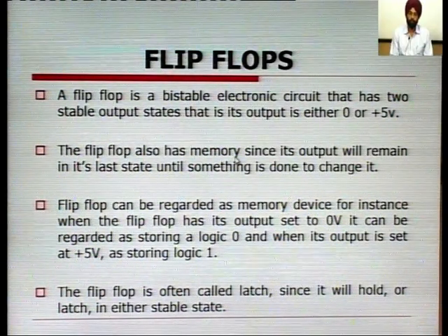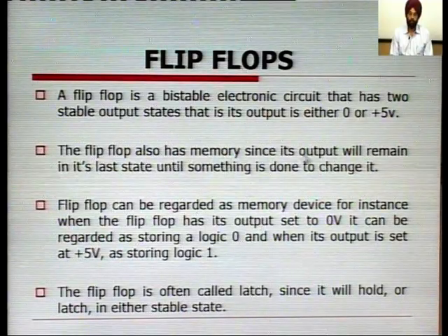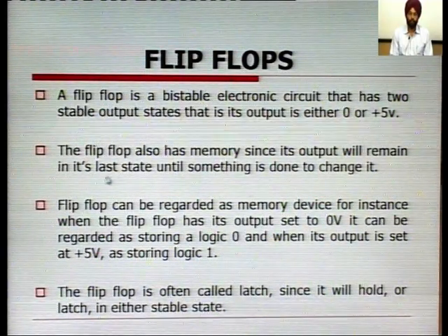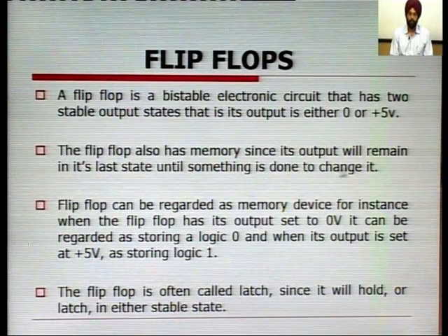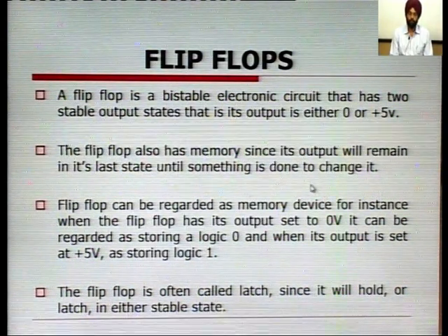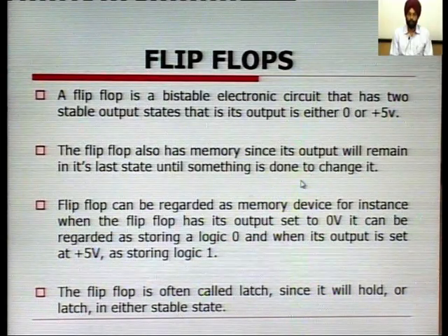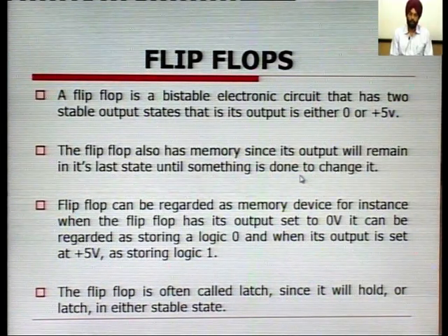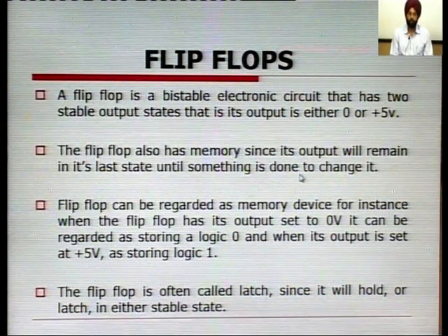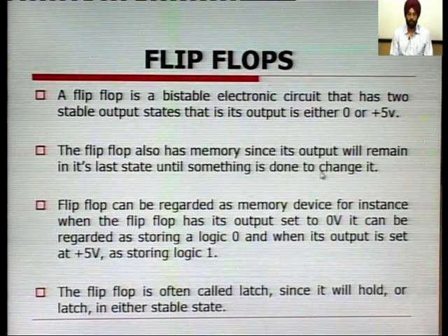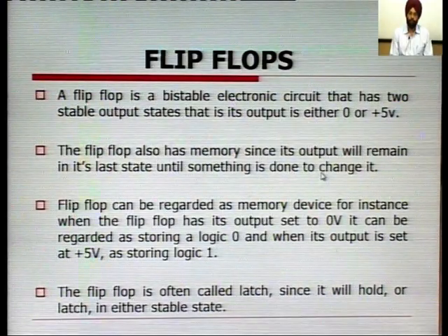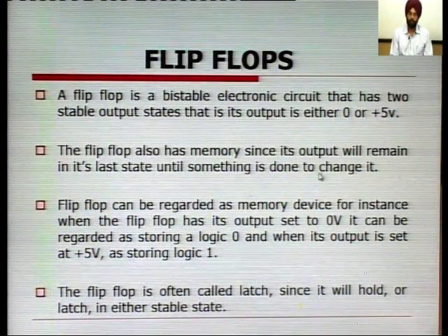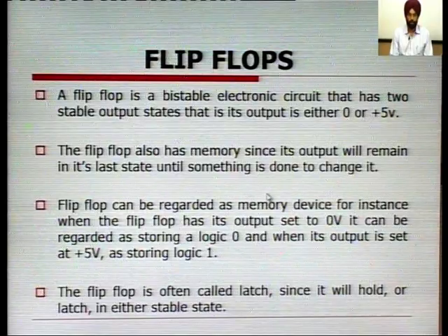The memory means its output will remain in its last state until something is done to change it. So, even if the input is replaced or disconnected, the output of the flip-flop will stay in the last state until and unless we apply some signal to change its output state.